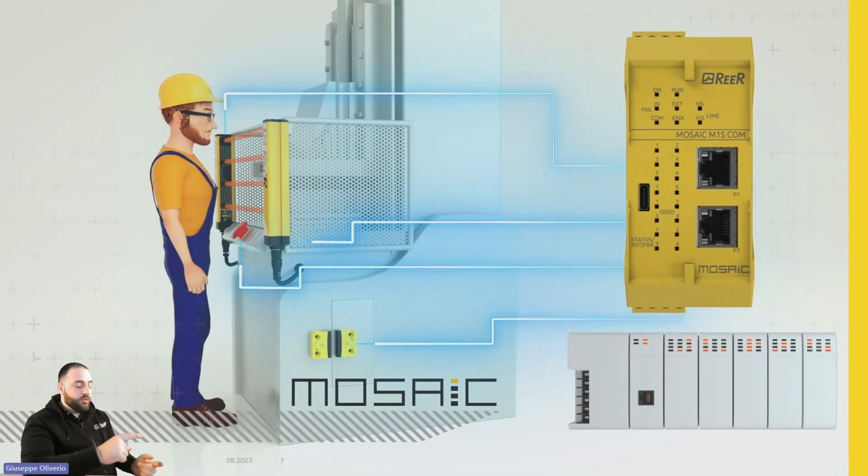You will see that you need at least one safety relay for each safety device, and one or more safety relays in order to do the logic and then the connection to the actuator. So you are adding safety devices, components, inside your cabinet. So it also increases the possibility of making mistakes.